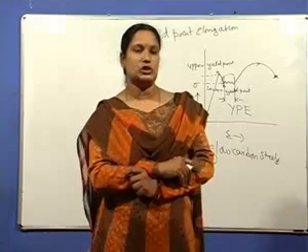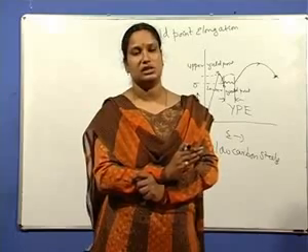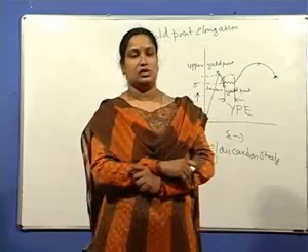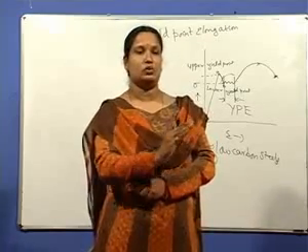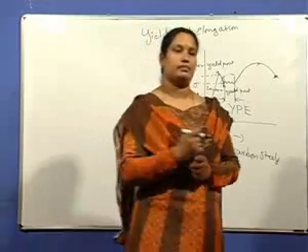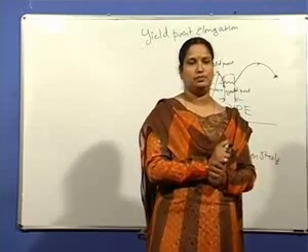These atmospheres act as a barrier to dislocation motion. They pin down the dislocations, so the dislocations have to cross these atmospheres. These are the obstacles for dislocation motion.